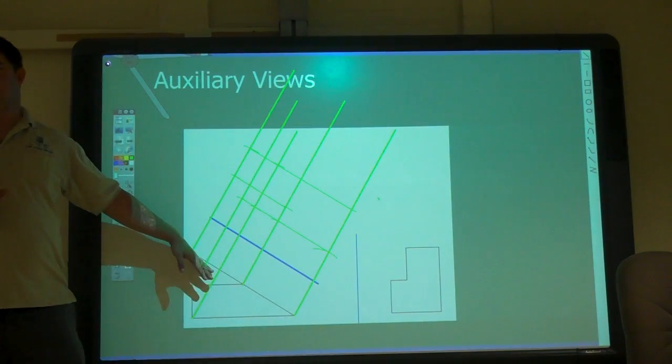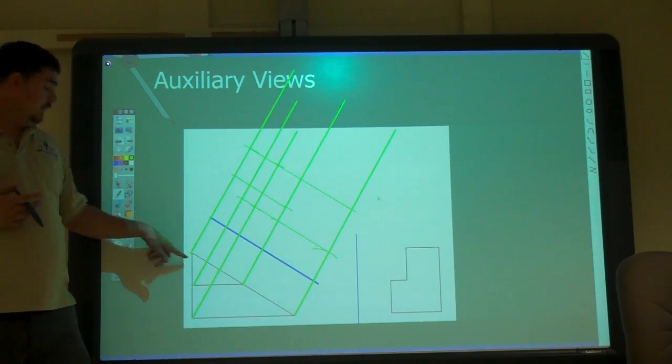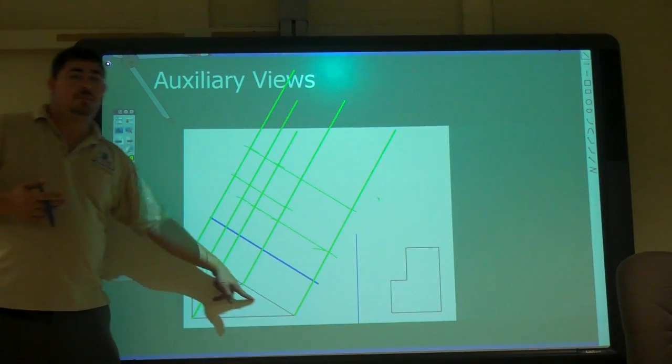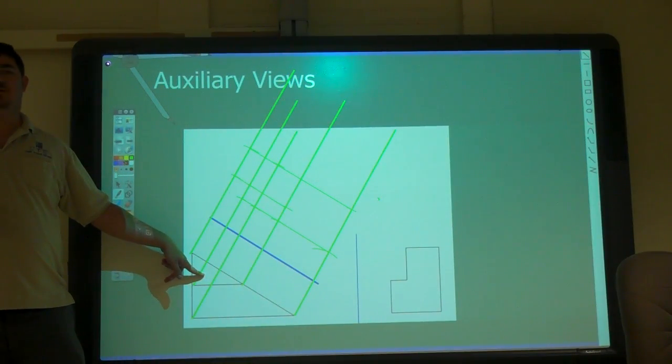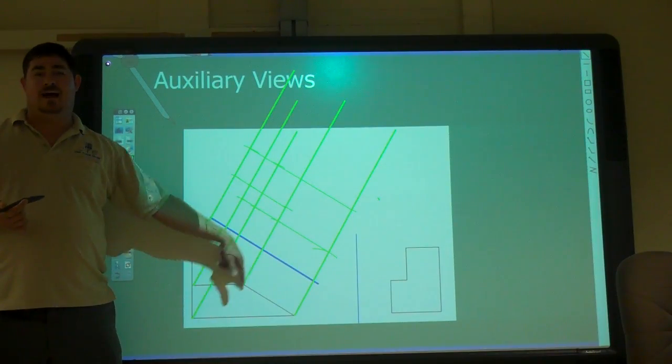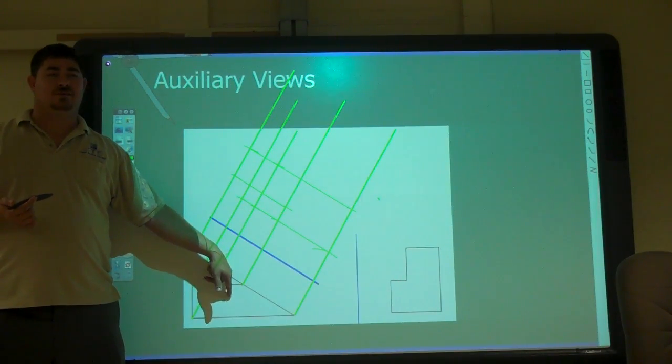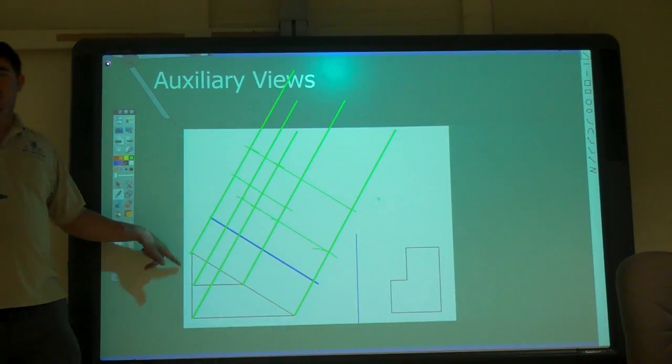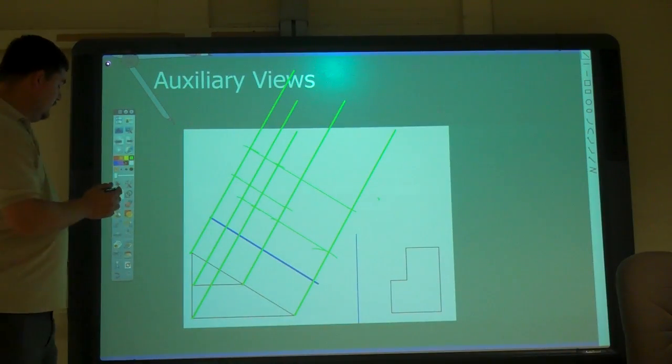We know those are all going to be visible, right? All the lines here on this front plane, they're all going to be visible. You guys agree? Yes? How do I know that all this is going to be visible? Solid one. Yeah, because if I'm pointing from the floating plane, it has to hit that first, right? So I know if there's a point on that plane, it's going to be visible. So let's draw that in.